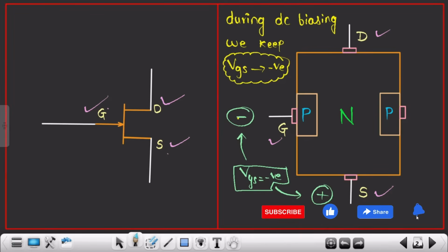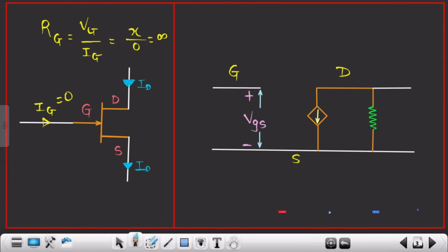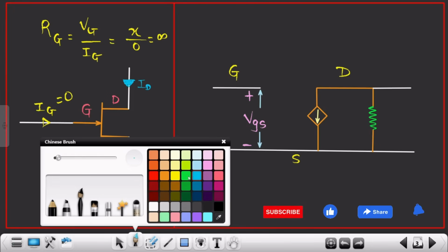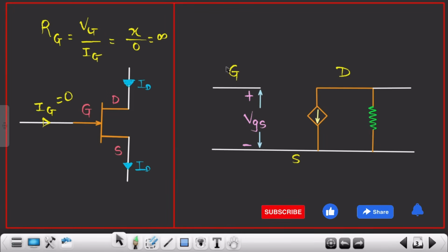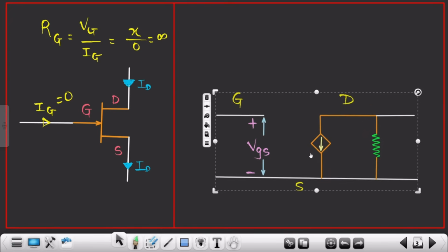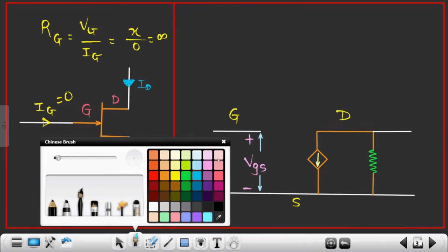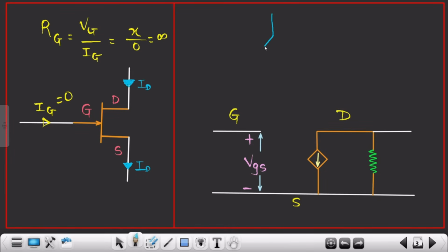That is the internal structure of the JFET. We are applying certain voltages, and due to that, the electrons that are available will only flow in this particular direction, and based on the direction of electron, the current will always flow in the opposite direction. So the current will flow in this particular direction only. All right, so how am I going to represent this current? Whenever I talk about AC analysis and the representation of current, let me move it a little down. If I want to represent a current source, I will represent it in this way.